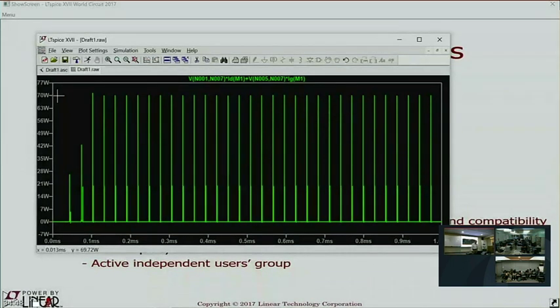Well, 70 watts is not a disco party. I mean, I've been calling these things power MOSFETs, right? They're not power MOSFETs. They're little tiny surface mount devices. You can't dissipate any power in these things, and they don't have a heat sink. So 70 watts isn't going to be okay. But it doesn't dissipate 70 watts for very long. Let's see how long it dissipates 70 watts for.